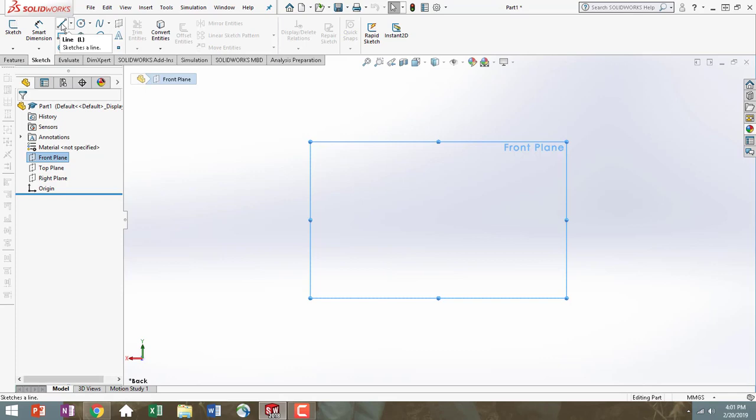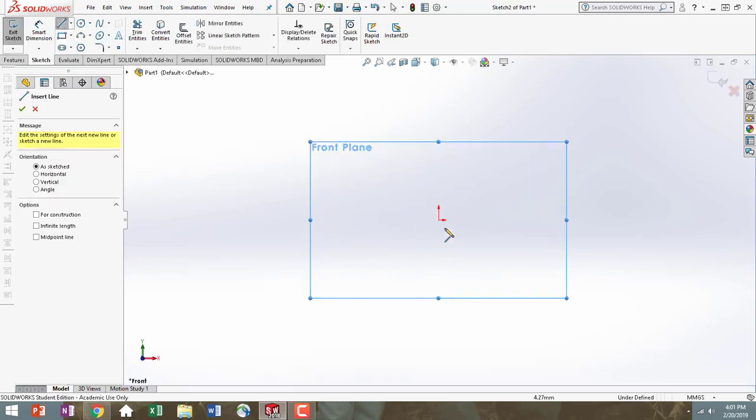I'm going to start by just making my simple design, and then we'll put in our equations. We are going to learn how to do an equation-driven part today. So the key to this is your side legs, only one of them needs to have a relationship. So you can have the bottom be set at a horizontal relationship, or this straight up and down one be at a vertical, but you cannot have both because your overall angle of A1 will be changing.